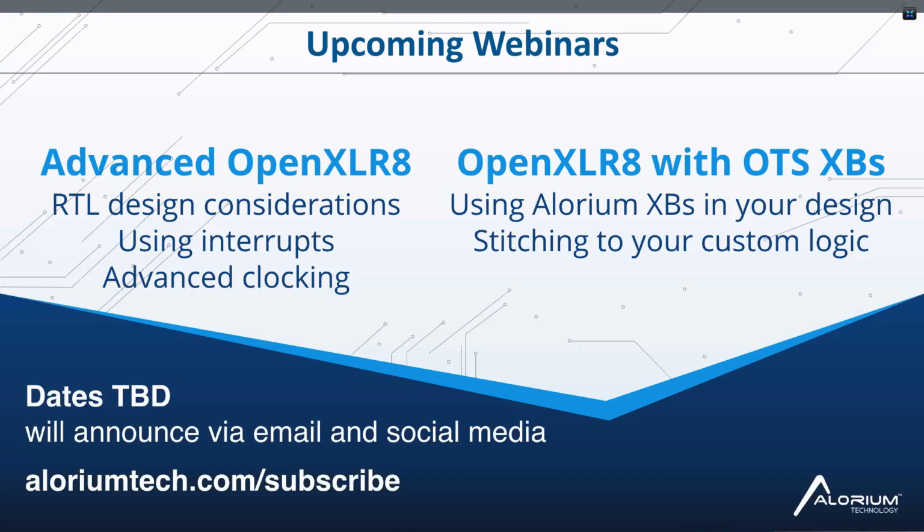as well as some advanced clocking techniques. Right now, we are basically just using the standard 16 megahertz clock that we're running the Arduino, or the AVR, on. But the chip is obviously capable of doing more than that, and we've got some examples from some of our engineers here, where they're running the clock a lot faster to power their logic, but we're still running the interface for the AVR at 16 megahertz. So we can get into some of that.